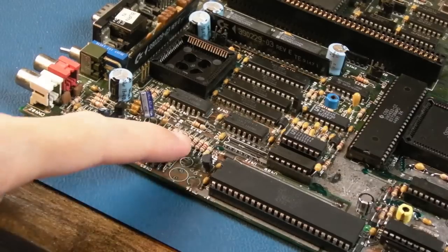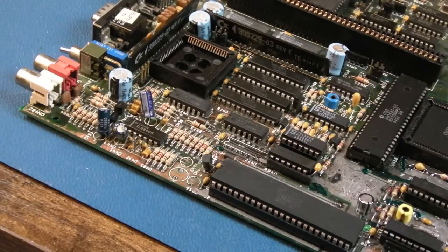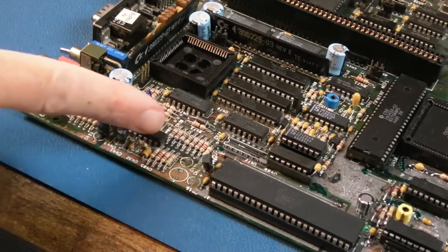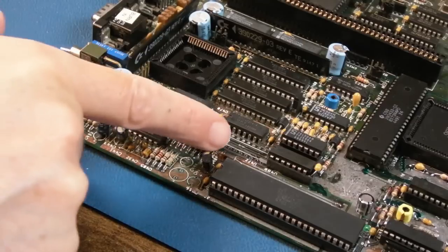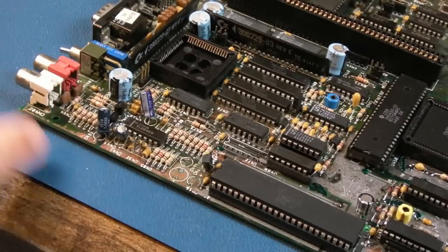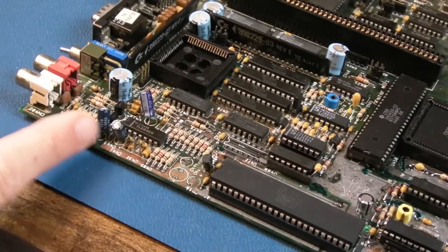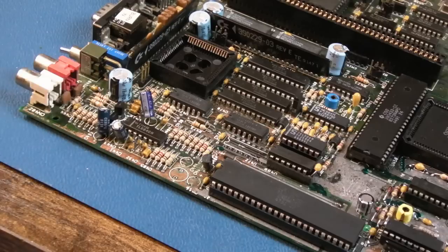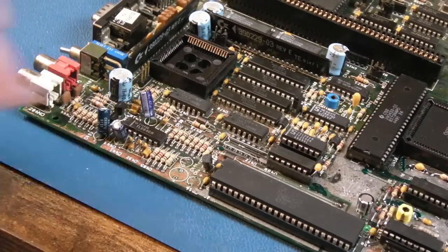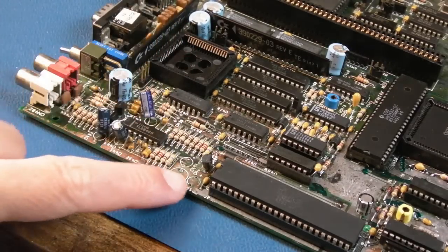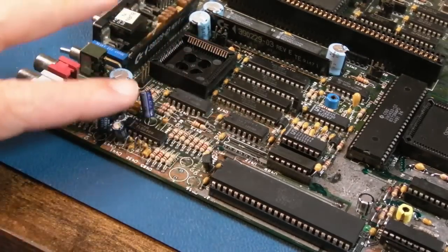Right, so I took the 3 caps off around here, going to replace those, but I'm now going to have just a bit of a clean up here. I'll scrub around with some vinegar, get right in and around these components, fiberglass pen, and do the same as we go along here. I think, swap some of these things out as well. I mean, it looks a bit greeny, we've lost the solder mask, but you know what, this area is a lot less affected.